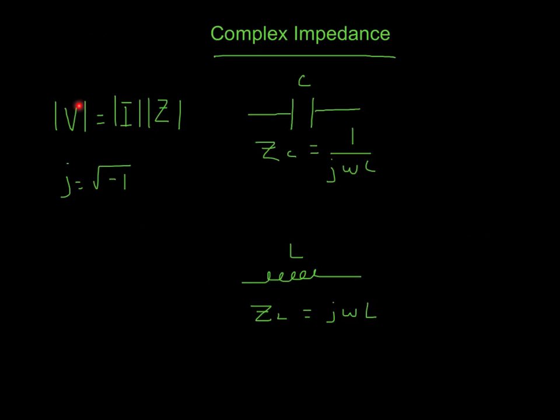But let's first talk about the complex impedance of a capacitor and an inductor, two reactive components as opposed to resistive. I should write down R, just to let you know nothing too fishy is going on. Z of R, that's for the resistor, is purely real, and it's just going to be R. Z of C, the impedance of a capacitor, is purely imaginary, and the complex impedance of an inductor is purely imaginary as well. What this means is these components are reactive. They don't burn up power, they just redirect it. So that's a very fundamentally different kind of component.